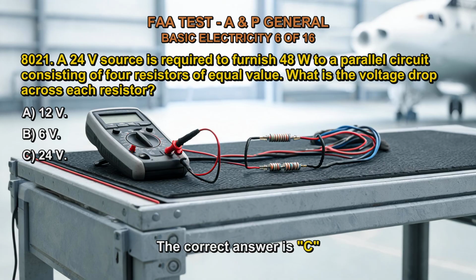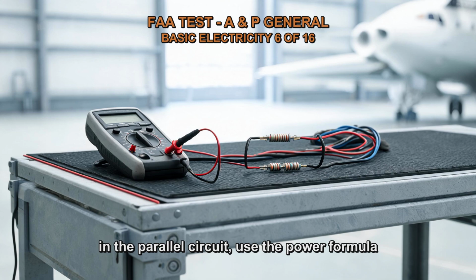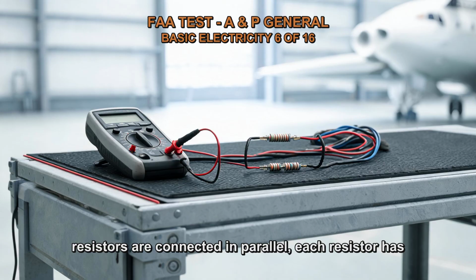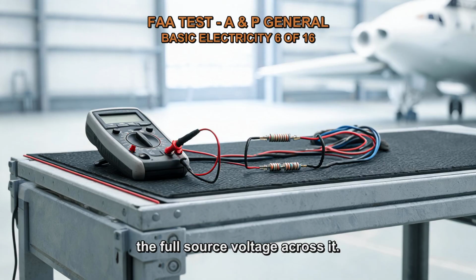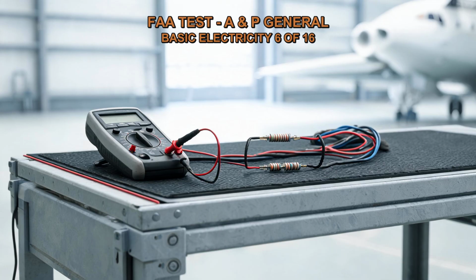The correct answer is C. To calculate the voltage drop across each resistor in the parallel circuit, use the power formula P equals V multiplied by I. Since the source is 24 volts and the resistors are connected in parallel, each resistor has the full source voltage across it. Therefore, the voltage drop across each resistor is 24 volts.